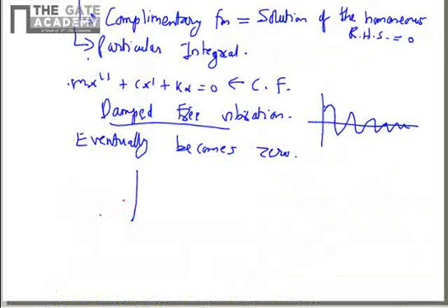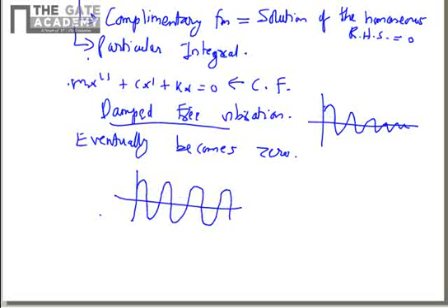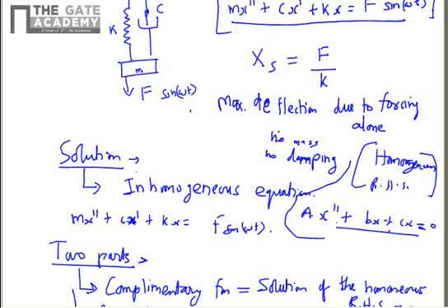So it can be easily demonstrated that the particular integral will be the real solution of the forced vibration case, and there the amplitude is not dying with time, and the amplitude x will be something different from the case of the free vibration. In the free vibration, by determining A and B from initial conditions, you can get the amplitude. But here the x will be something different. The x will also be different from the simple plain forcing case.